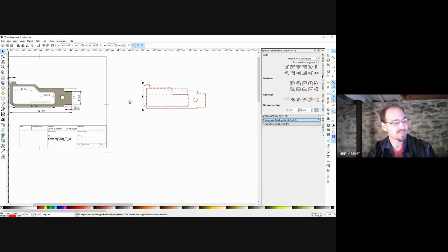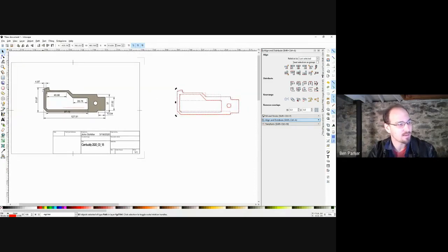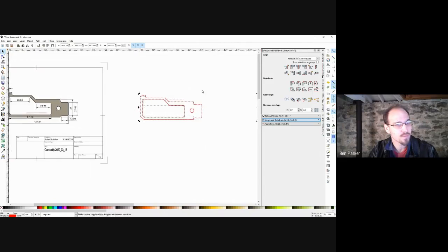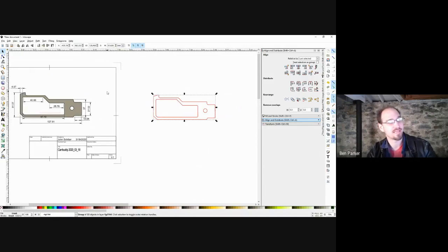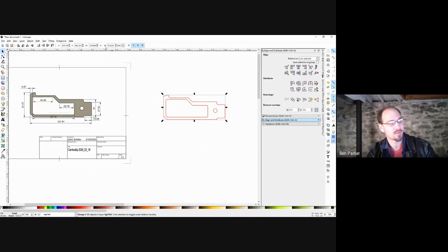So John was asking about scaling. We can flat out set the height of this. So this is 51.07. I'm going to select the whole thing. And it's already 51. Actually, John, I think it came in at exactly the right size, or pretty close to it. We're going to set this to 51.07, but we want it to scale the same width as well. We toggle this, it'll keep the same proportion. So height of 51.07 mil. There we go. That's it. And then that should be able to cut out very directly with the laser cutter.